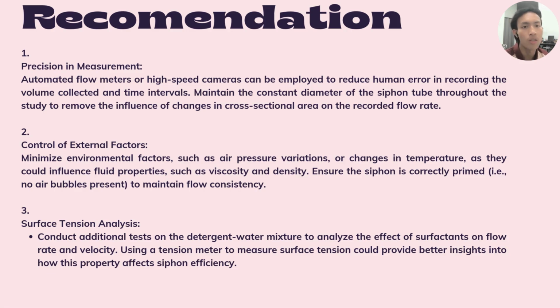Number 3, surface tension analysis. Conduct additional tests on the detergent water mixture to analyze the effect of surfactants on flow rate and velocity. Using a tension meter to measure surface tension could provide better insights into how this property affects siphon efficiency.